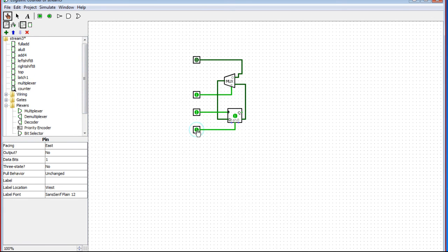So you have to enable the flip-flop, otherwise it's not going to change at all. If you enable the flip-flop, then you're enabling the value to change. This enables toggle mode, which means whenever you clock, it's going to switch from 0 to 1, 0 to 1, 0 to 1. Doesn't matter what this is, it's not being selected. If you select this to 0, that means you're in load mode. When you clock, this value gets put in the register. So if it's a 0, now it becomes 0.